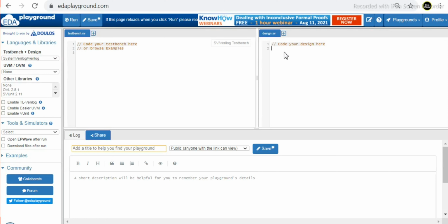Well, in this video, I'm going to teach you how to code for the flip-flop. So let us go ahead and start coding with the design. As usual, module and then the flip-flop, name of the module. We have to list down the ports: clock, reset, D and Q. So these are the signals in the D flip-flop.